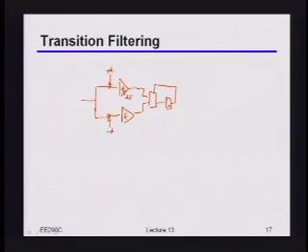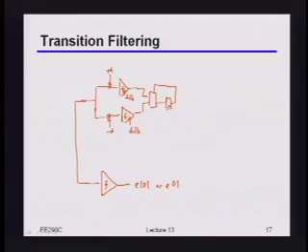Okay, so this again may be your data path. But then what you could potentially do is, on your edge path, instead of having all 3 of those samplers, you'd only have 1, right? But then you say, I'm only going to use this thing when I know that I actually had a clock pattern, right? When I know that I had a 101 or a 010, so that I know that the timing information is reasonable. In fact, you can keep on extending this to more and more taps. So you can make it so that you only do your timing estimates based off of patterns that you know should have good information given whatever it is that you were doing in your equalizer.